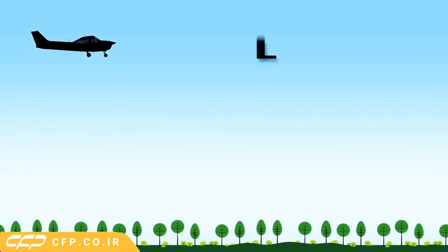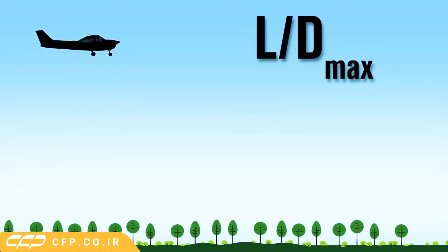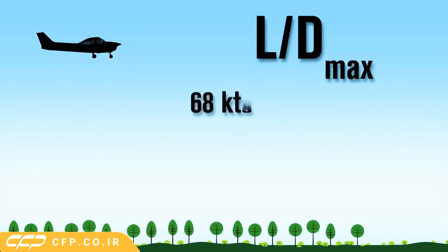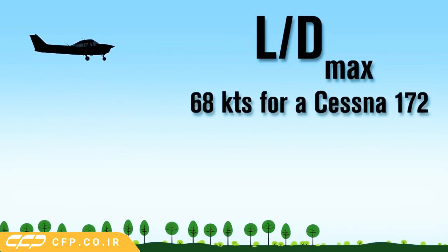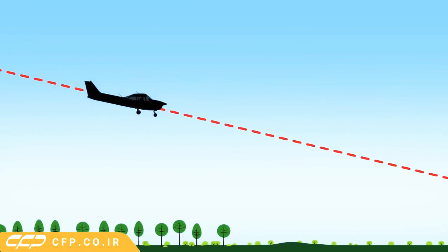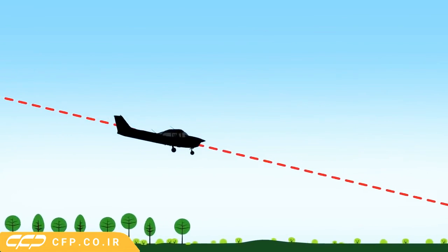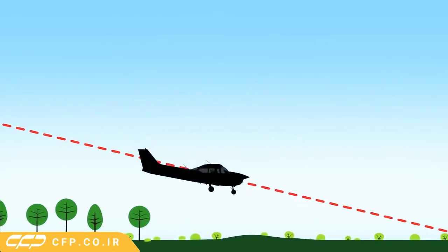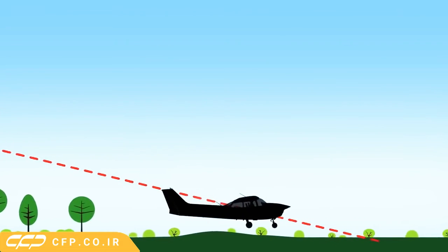Pilots should be familiar with this number, because in the unlikely event of an engine failure, this is the speed at which they'll want to glide down to the ground. In a no-wind condition, this speed will give the pilot the best glide ratio, meaning that they'll be able to stay aloft the longest to maneuver to their intended field for emergency landing.